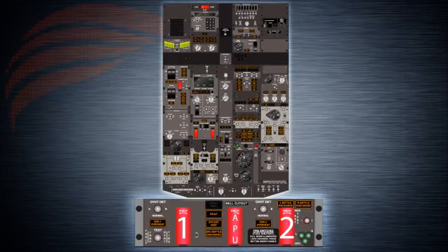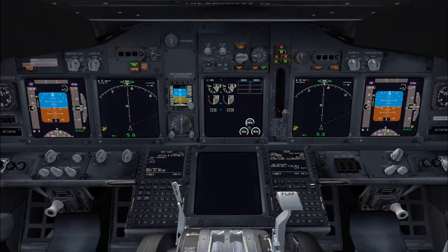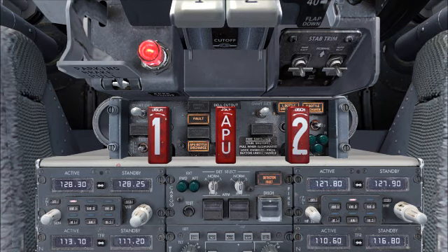So that's all of the system annunciator panel lights covered now, and you can see that almost every single amber light on the flight deck is covered by this system. Many of those excluded are on the forward panel, where they would be within the crew's normal visual scan anyway. Also excluded are 4 of the amber lights on the overheat fire protection panel. The fault, APU bottle discharge, and the left and right engine bottle discharge lights will not trigger a master caution. The detector fault light on the cargo fire panel is also excluded from the system.